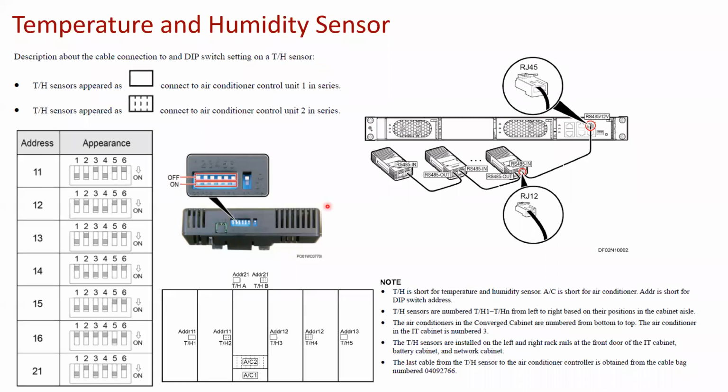So these sensors are especially designed for controlling the entire inside of the data center and outside of the data center. So you can see some sensors are placed outside and some sensors are placed inside. The basic purpose of these sensors is capturing the humidity and temperature readings in the data center. So you can see in this example, if I have a 5 rack arrangement, I can put a sensor on each rack. Each rack I'm putting one sensor, and air condition 1 and air condition 2 have the connection. So you can see here the line AC2, which has its dedicated